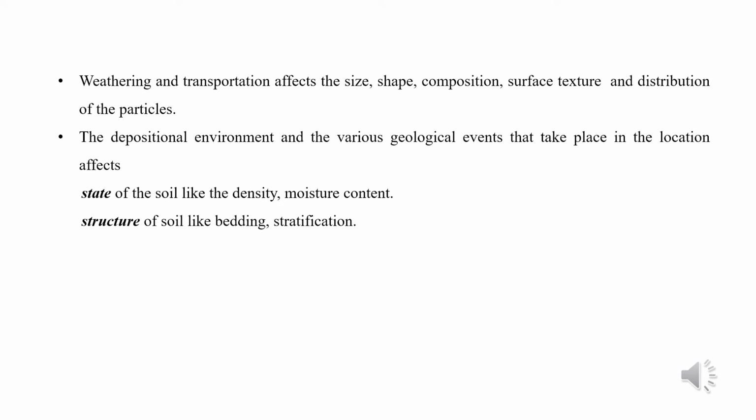Moreover, the depositional environment, the way the soils are deposited or redeposited at a place, and the various geological events that take place in the location also affect the properties of the soil. Like the state of the soil, the density, the moisture content, or the structure of the soil, like how the soils are stratified, or the bedding of the soil. So it will eventually affect the various engineering properties like the shear strength or the permeability of the soil. So we'll talk about it in detail later in this lecture series. Okay.